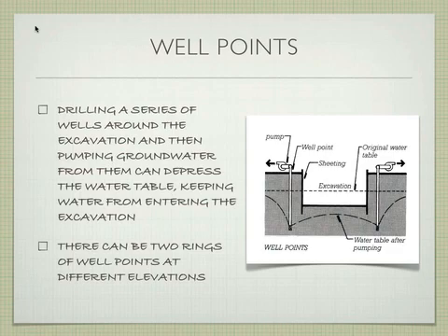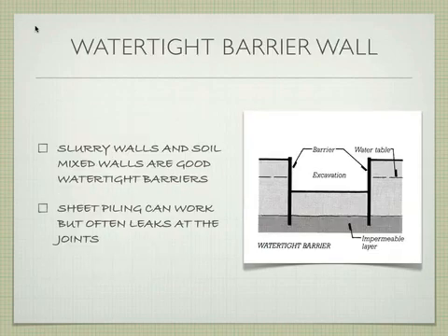So we already talked about there can be several rings of these pumps. Now recognize if you have a very small site, and you're trying to do this excavation, and you need to drill these well pumps, and you don't own any of the property around it, it's kind of challenging to drill all the wells that you need. So there are challenges. You need to have enough space to do this method in the first place.